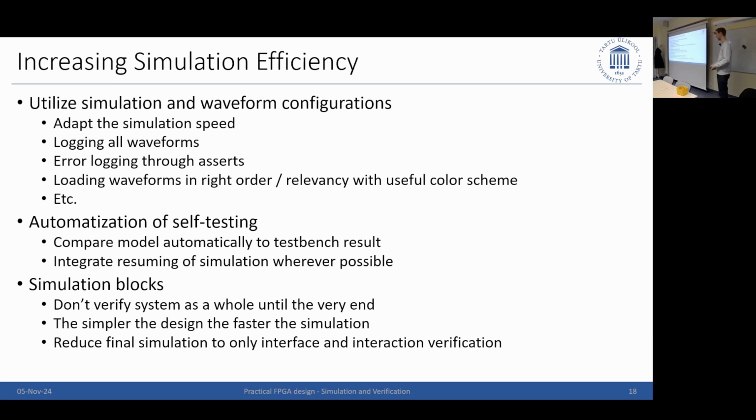But as a verification approach, you also have to consider that each of these test benches and verifications takes additional effort, so it's a balance. How long does my verification take? How much do I rely on my design? What if I just need to run place and route once and it takes me days, but it also takes me days to take this design apart and make it smaller to run the approach in a few hours? You need to make an assessment of what is more time efficient. Having a computer run on the side is easier than having actual man time on designing things.